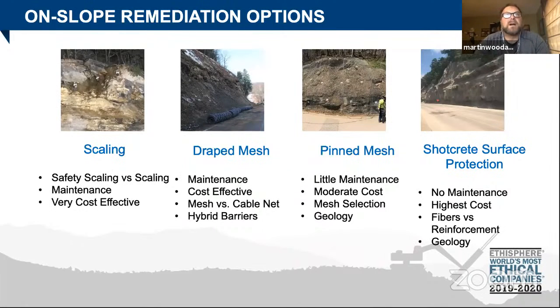But I want to spend some time on these on-slope treatments because these are the most common and cost-effective ways of dealing with them if you can do it. So we're going to be talking about scaling. If anybody hasn't seen scaling, it's a lot of fun to watch the scalers up there. They go up there with pry bars, and I'll show you some cases of it, and they remove all the hazardous rocks. And we want to think about that as the starting point.